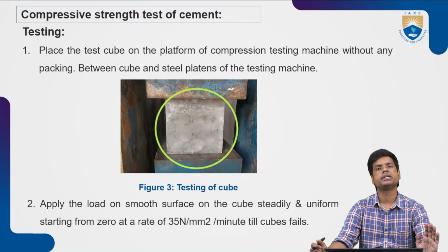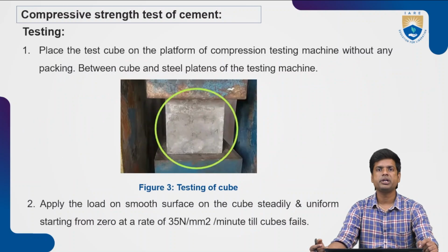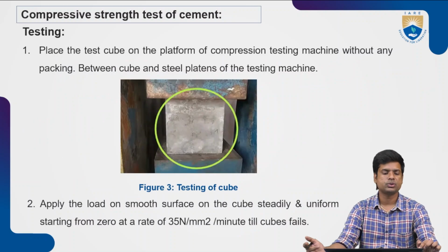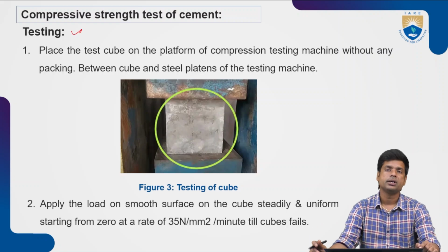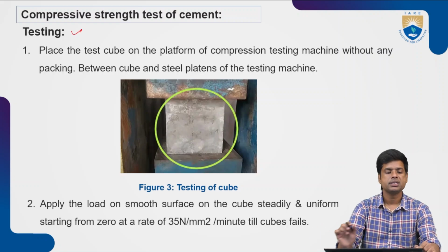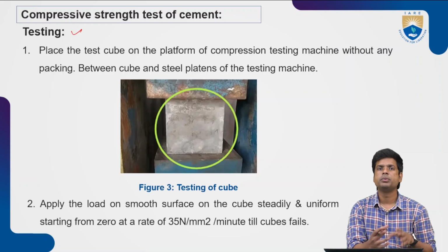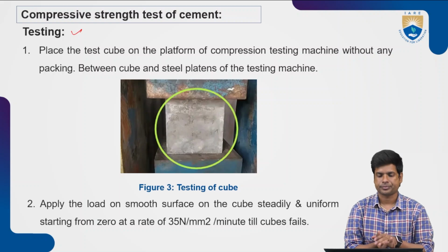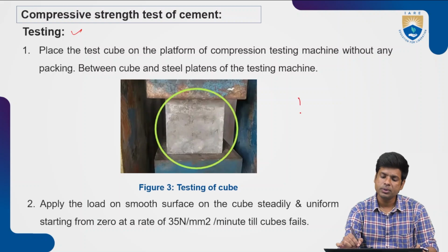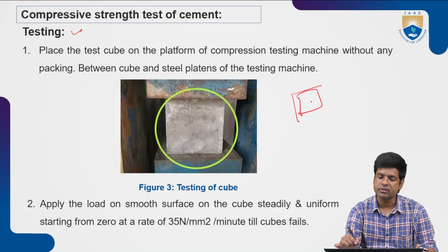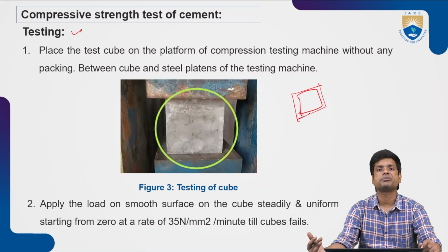With this we have completed the casting of the cement mortar cube. Now we will go through the testing of the cement mortar cube. After preparing and curing the cube, take out the cube, and before testing, wipe off the moisture around the surface of the cube.